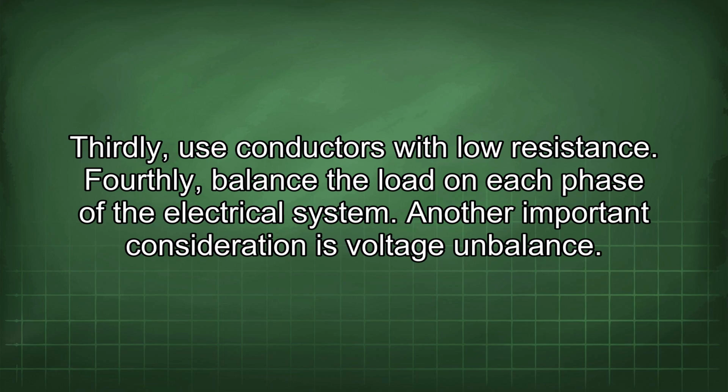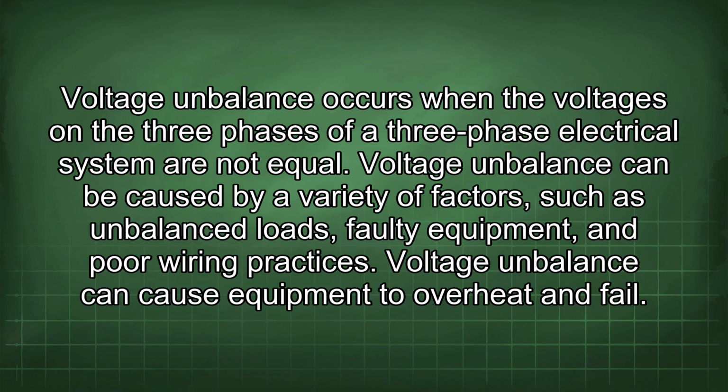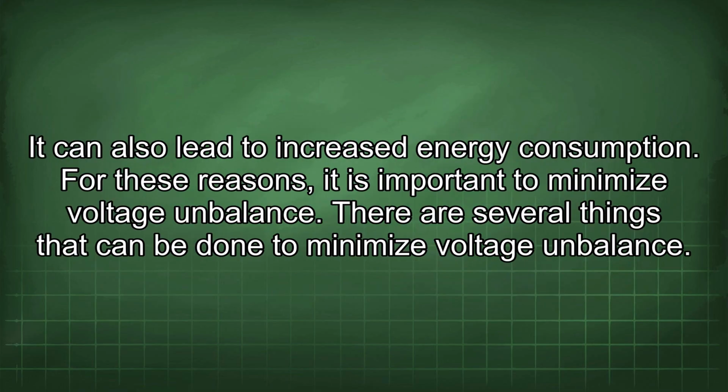Another important consideration is voltage unbalance. Voltage unbalance occurs when the voltages on the three phases of a three-phase electrical system are not equal. Voltage unbalance can be caused by a variety of factors such as unbalanced loads, faulty equipment, and poor wiring practices. Voltage unbalance can cause equipment to overheat and fail. It can also lead to increased energy consumption. For these reasons, it is important to minimize voltage unbalance.